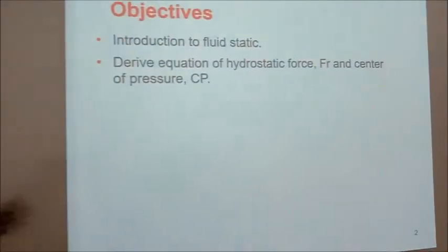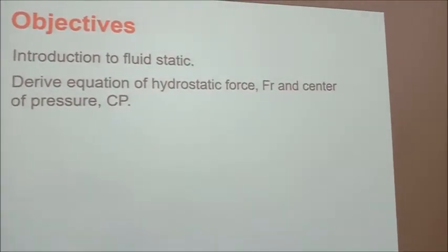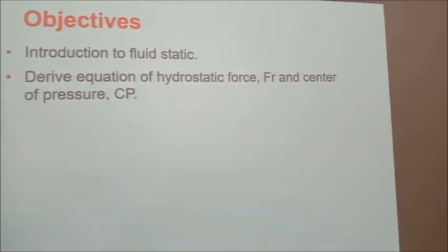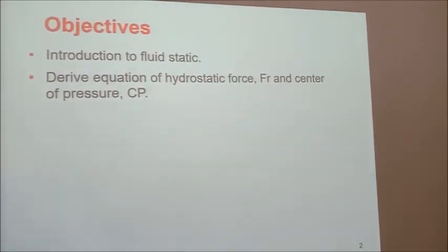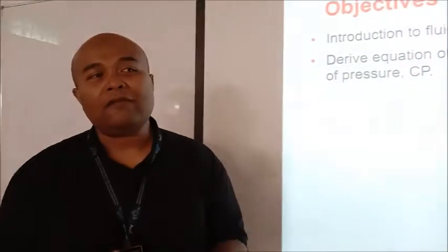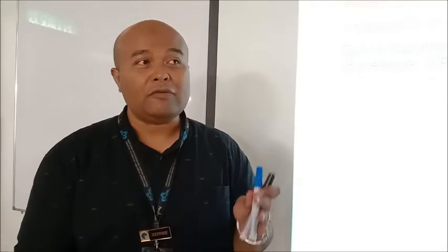So for the first objective, I will give a very brief introduction about the fluid static. At the end of my lecture, I'm hoping that my student able to differentiate between the fluid static and fluid dynamic. So basically, fluid static is any study related with distribution of force, load and pressure to fluid when the fluid is at rest condition. However, on the other side, fluid dynamic is the study when the fluid is at the moving condition.